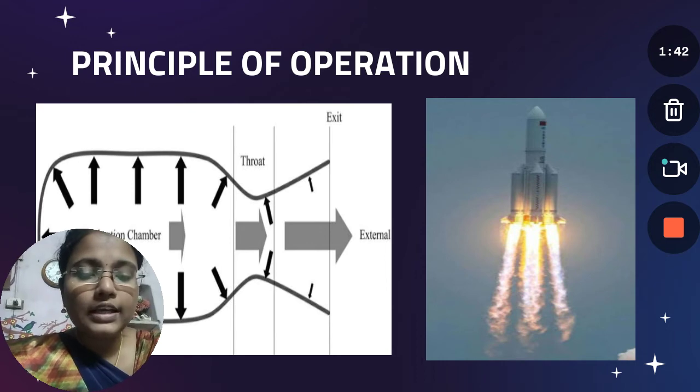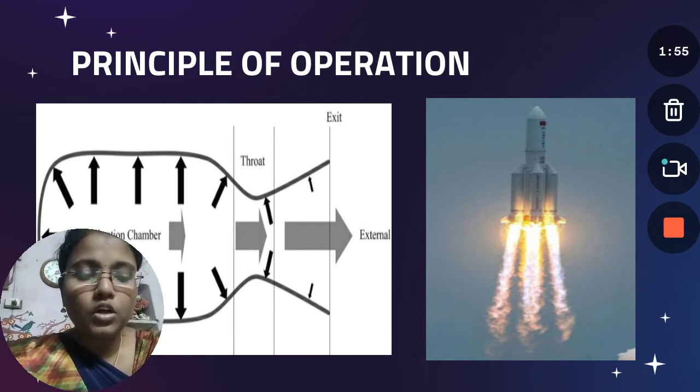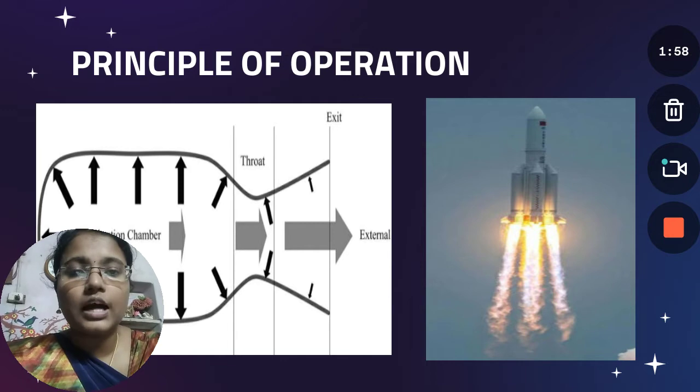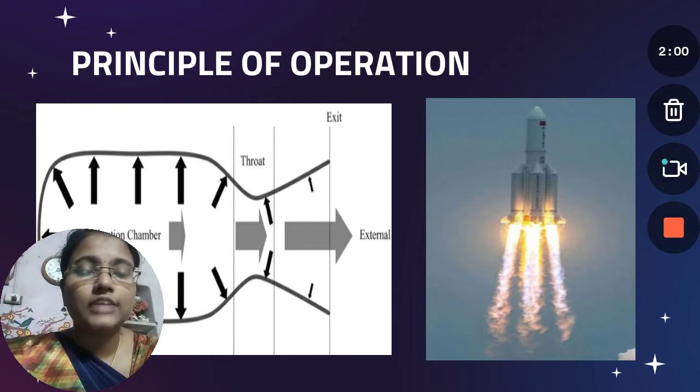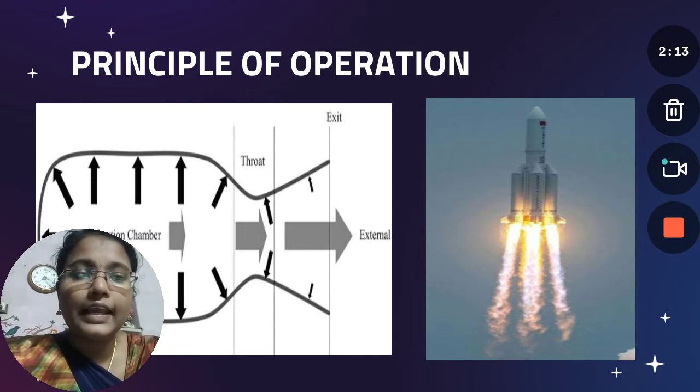By providing an opening at the bottom of the chamber, there is no pressure acting on that side, but exhaust escapes from that end. The remaining component of the pressure produces a thrust on the side opposite the opening. Using a nozzle increases the force further, in fact multiplies the thrust as a function of the area ratio of the nozzle, because the pressures also act on the nozzle.